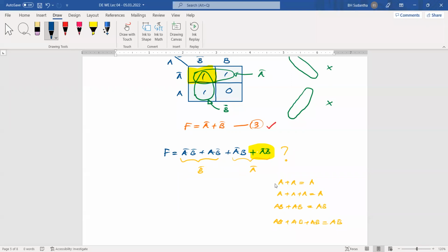So we have taken A bar B bar 2 times, assuming that in our equation we have A bar B bar 2 times. But actually, in our equation, we don't have that. But if you assume like that, there is no harm. We haven't done anything wrong or illegal. This is allowed. Actually, that is the first rule of the concept: one term can be covered many times. But remember, you can do this only if it helps minimization.